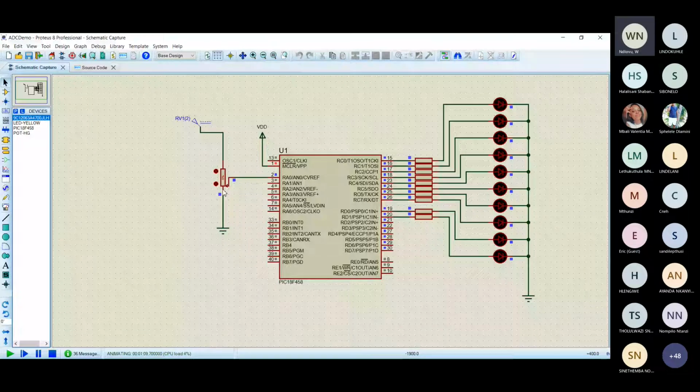And that voltage is a fraction or a percentage of 5 volts. Until when this arm is pointing at maximum there, I'll be sending 5 volts there. So what we are doing here, guys, is taking this fraction of resistance, converting it to voltage, and displaying it as a digital output on the outside.